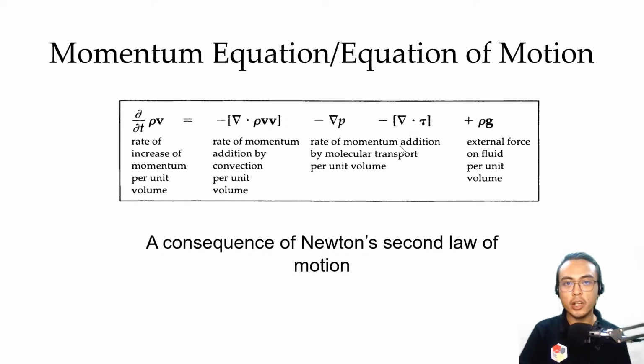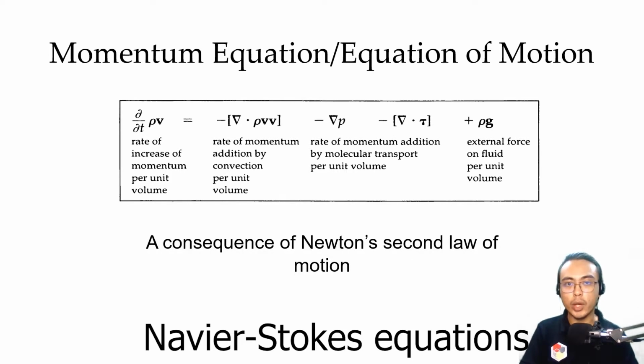The next term here represents the divergence of momentum flux or shear stress tau. And the last term represents the external force on fluid per unit volume. This is mainly the external force exerted by gravity on the flowing fluid. So if this vector momentum equation is a little too much for you, don't worry, because this has already been simplified for you. We call those the Navier-Stokes equations.